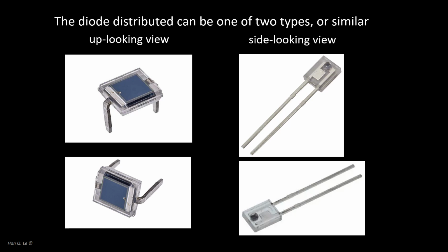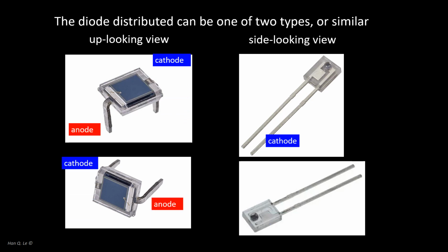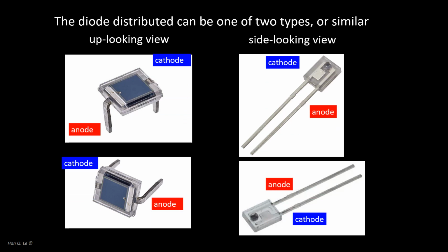It is necessary to identify the 2 terminals, anode and cathode, similarly to the LED. However, the leg length convention for the LED is not used for photodiodes. Instead, there is usually a band-like marker on the cathode. Shown in the figures is the cathode marker for each type. One can use a diode checker on a digital multimeter if in doubt.